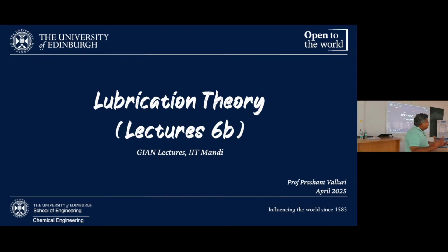Okay? That's what happens in so-called laminar flow. So at low Reynolds numbers, you don't have enough kinetic energy to drive these waves. Everything gets dissipated by viscosity. Okay? So that's why in microfluidics, you will not have much of a turbulence case. So that is giving you the information on the state of the system.